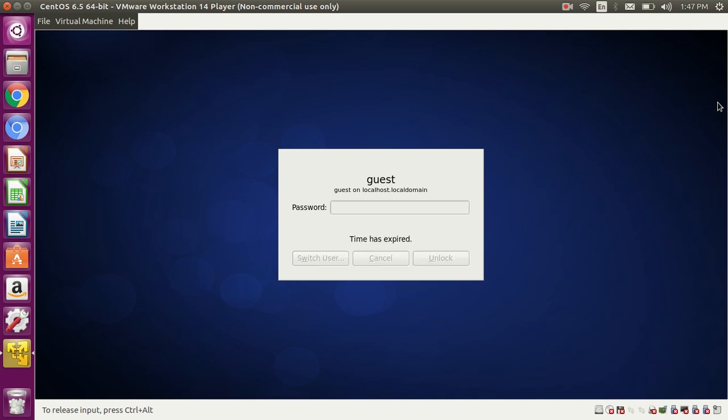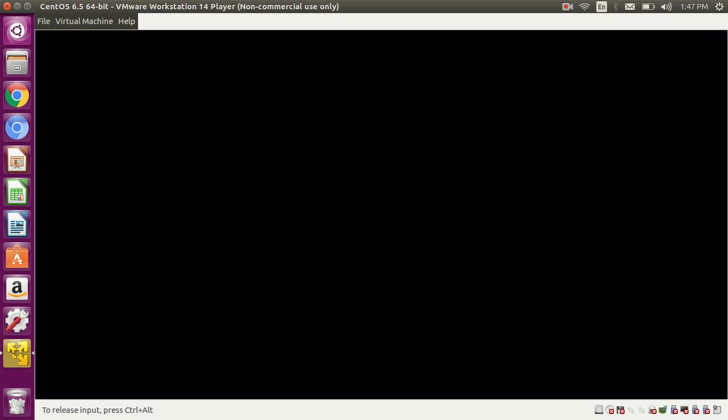That means from low to high. At this point it will not take. At this point only it will take. Sorry, whenever the clock is coming to low. Whenever the clock is high, this enable will not go to the output. However, this enable is always 1. So whenever the enable is 1, it will give 1, and the clock is stable because it is a negative level latch. Whenever the clock is going down, this enable signal will be at the output.